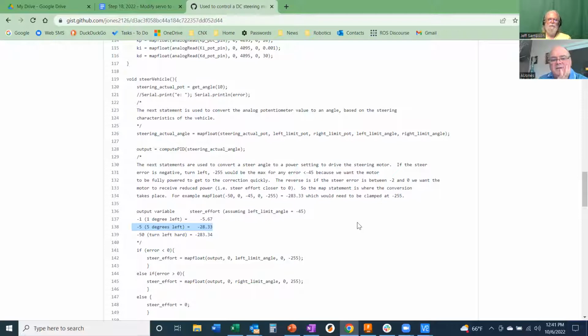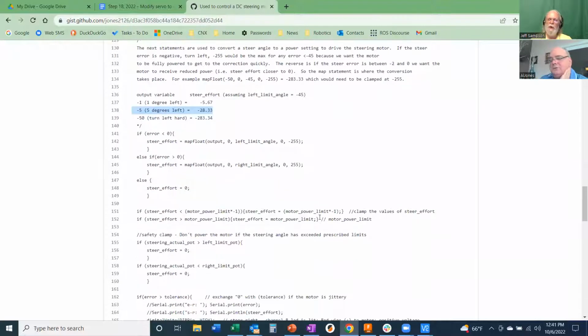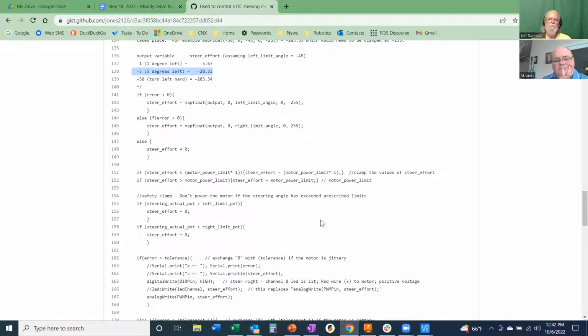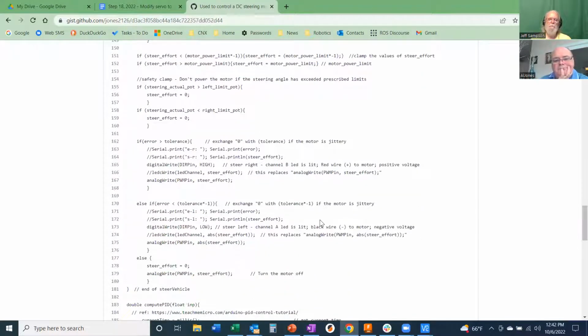That's not the way it's supposed to work. Meaning, if you're only off 1 degree, it's not supposed to get less power. No, I'm saying you shouldn't run your PID and then throw that away completely and put your own algorithm in on top of that. I'm saying take the PID output, and that's your value to send to the motor instead of trying to do any remapping on that.